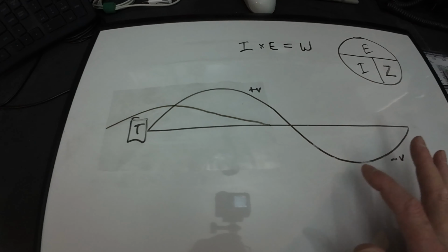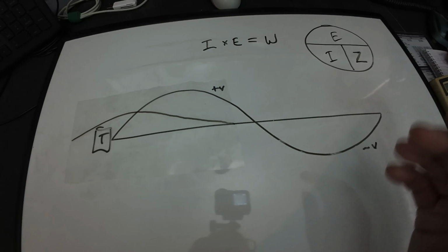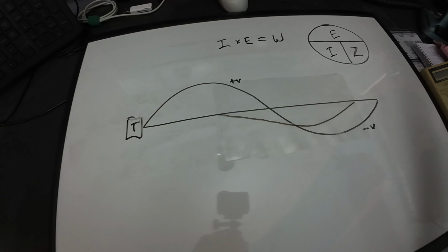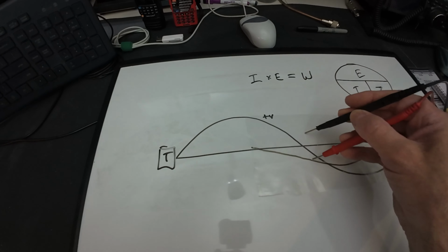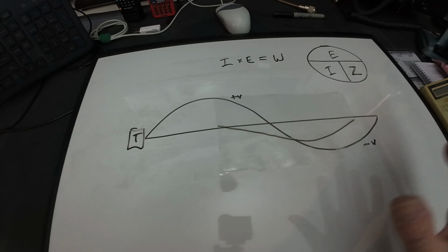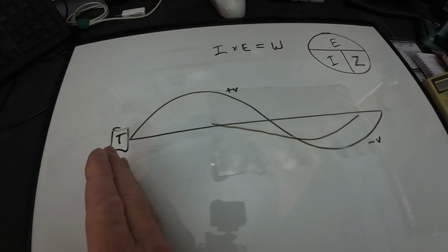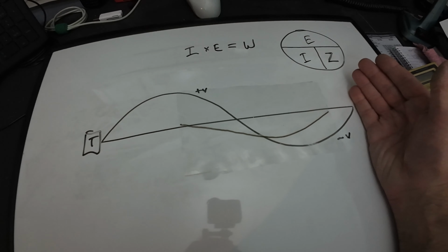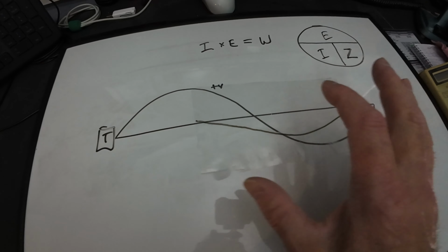So in this 67-foot piece of transmission line, as we check it in different places, it's going to have different impedances. So if we take our same nano VNA and we start checking this thing in different spots, we're going to get a different impedance reading depending where we are on that coax. Now we haven't talked about reflections yet, but that's going to happen, because if we're transmitting into 50 ohms of transmission line and it reaches a target impedance that's not 50 ohms, there's going to be a huge reflection that comes back and creates a standing wave.